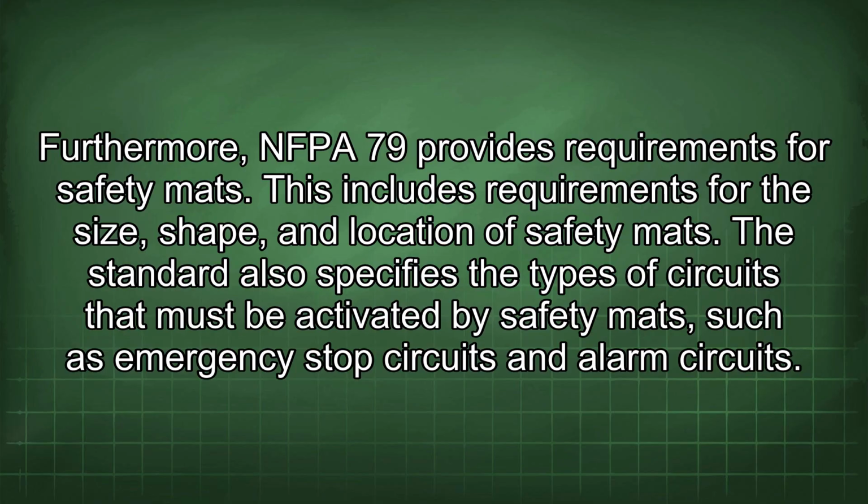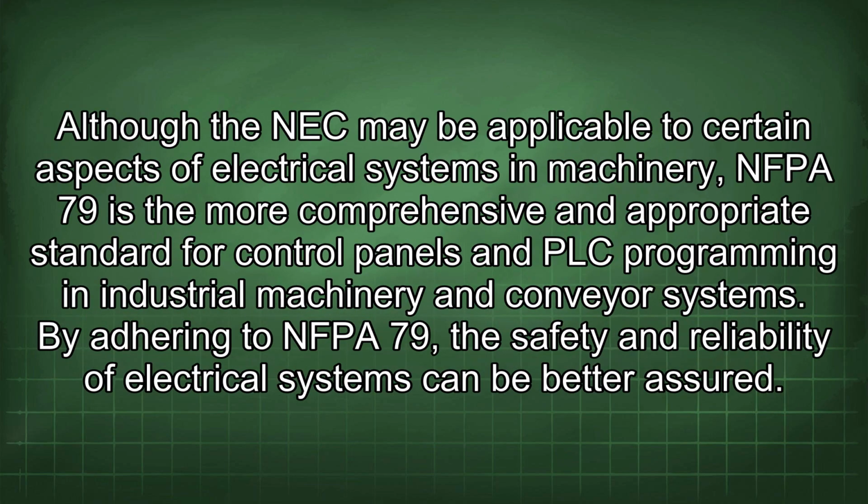The standard also specifies the types of circuits that must be activated by safety mats, such as emergency stop circuits and alarm circuits. Although the NEC may be applicable to certain aspects of electrical systems and machinery, NFPA 79 is the more comprehensive and appropriate standard for control panels and PLC programming in industrial machinery and conveyor systems. By adhering to NFPA 79, the safety and reliability of electrical systems can be better assured.